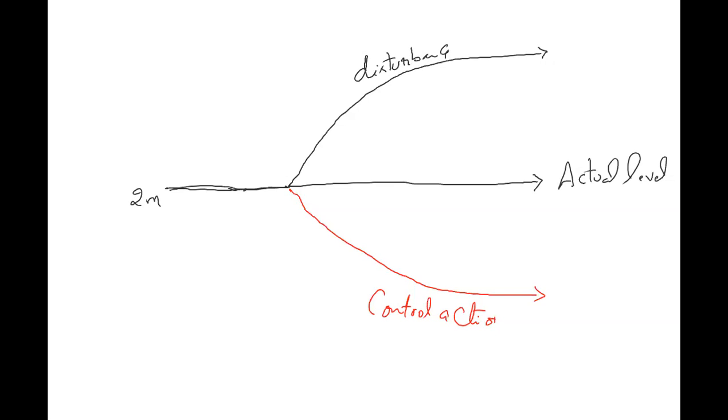See, the control outlet is the primary control variable, because that is your objective, no? What is the primary control variable? Your objective is to control the concentration, not the cooling water flow rate. The cooling water flow rate is what you are manipulating. Suppose somebody asks, why did you put the control system here? My objective of the control system is to control the concentration at the outlet of the reactor. Is it or not? So that becomes your primary control variable.